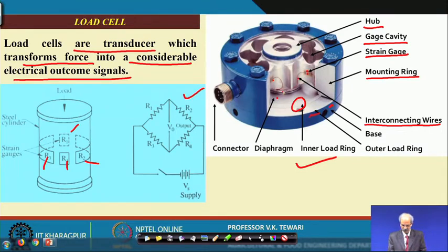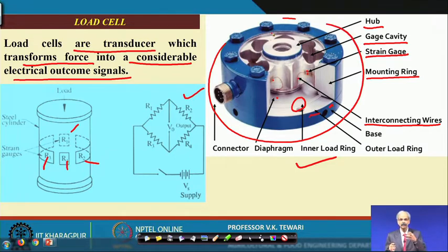So, this is the whole construction of a load cell, where in a very compact way it has taken the strain gauges, and you do not have so much of the electrical wires which were there in the earlier case. This is very compact and very handy to use, and it is available in various capacities of 10 K, 20 K, 50 K and so on. So, these can be used. Now, we will see how we have utilized this for developing a 3-point linkage dynamometer at IIT Kharagpur.